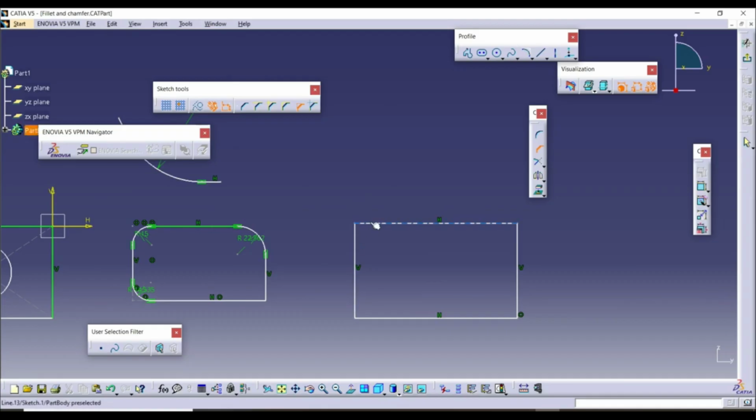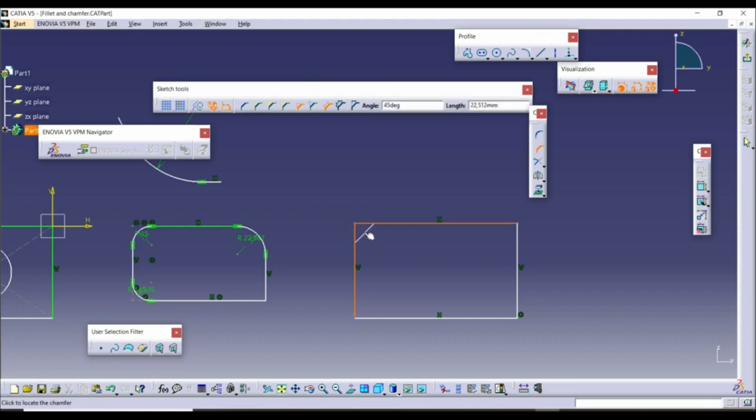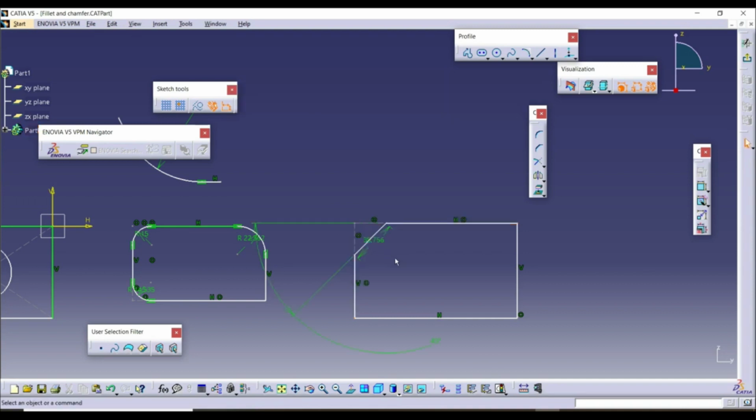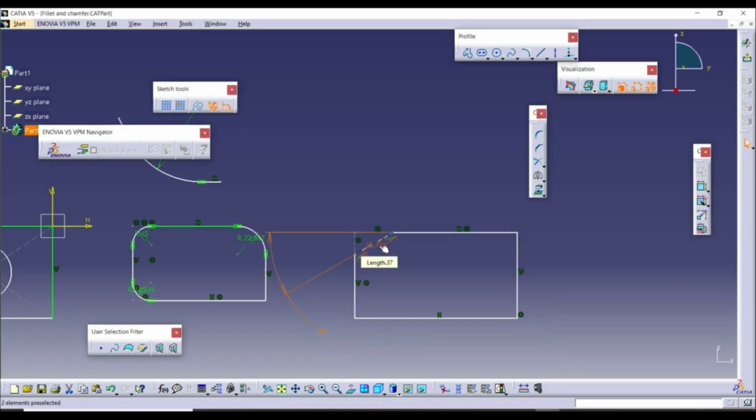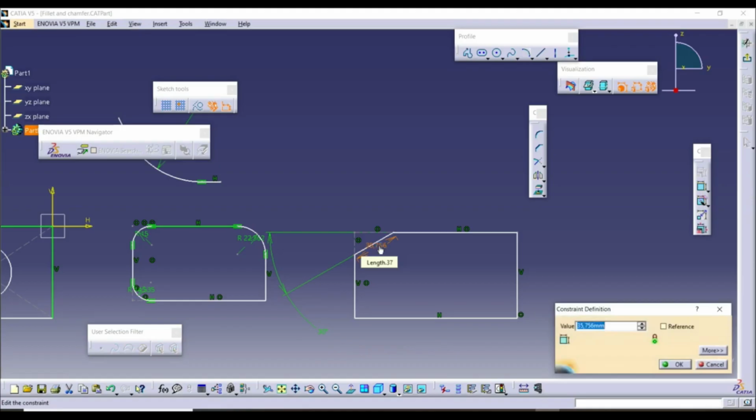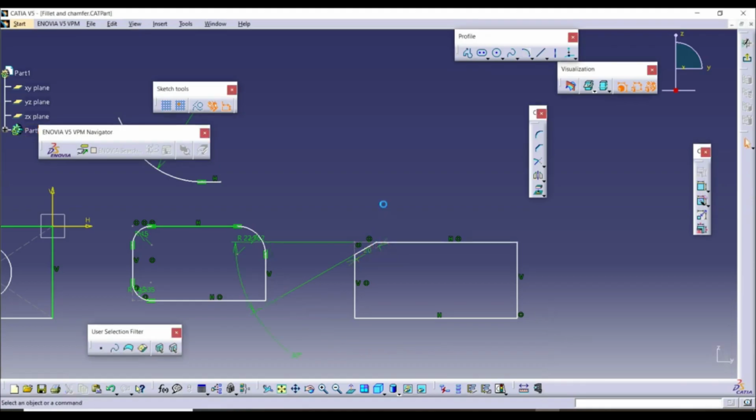So let's go here with this line and this line here, like this. As well, we can position this line here, here, here, and here. So let's go here, like this. And now here we have an angled line. We can change the angle here, as you can see. Now it's 45. We can double click here, go with 30, hit enter, and you can change the length here. So we can go, for example, with 20 and hit enter, like this.